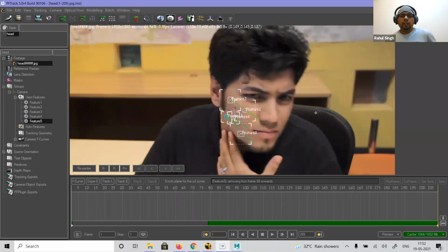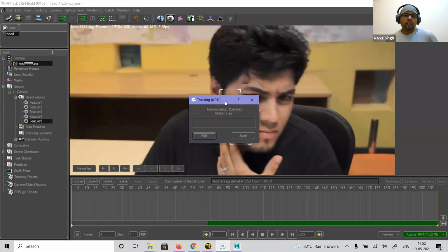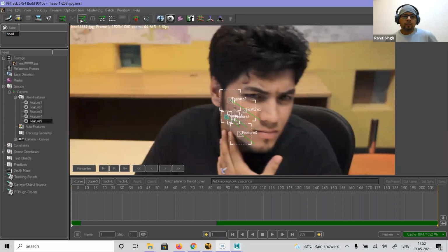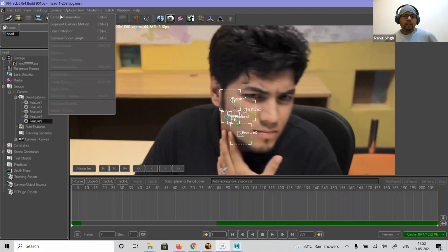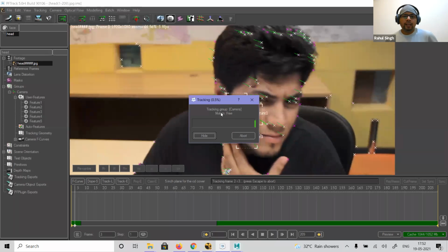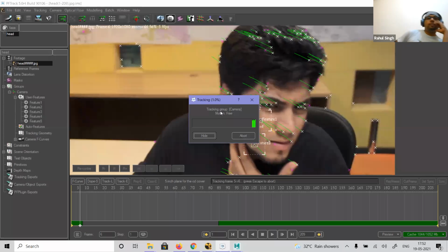Okay, so let us try to solve the camera now. It won't be solving it, right? Because points are less. So what I'll do is I'll add auto tracking to this.